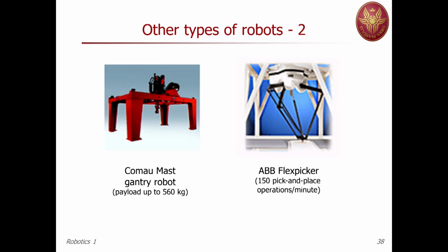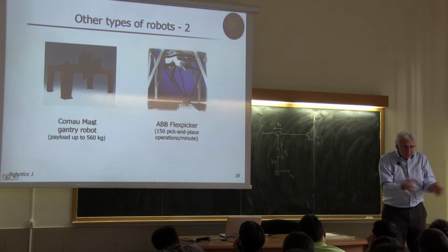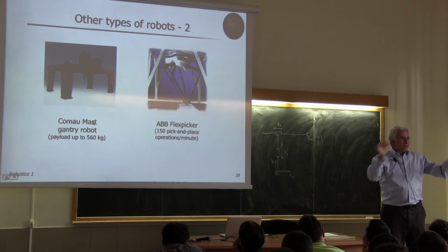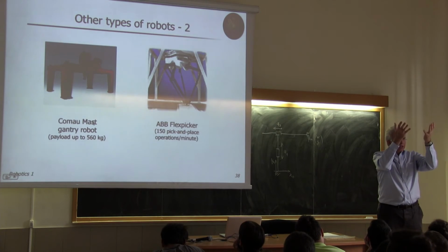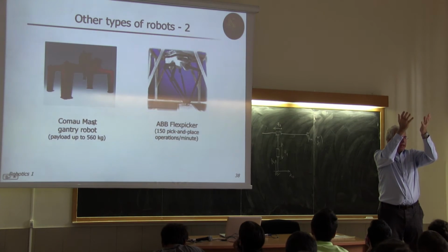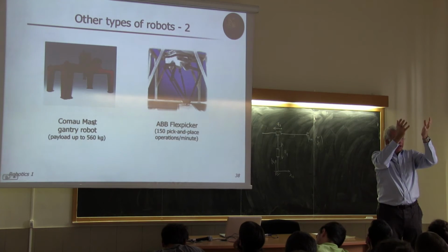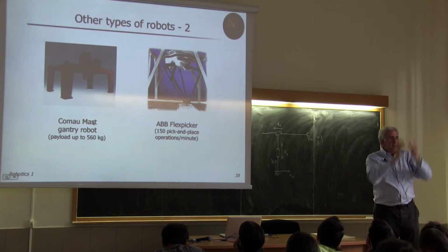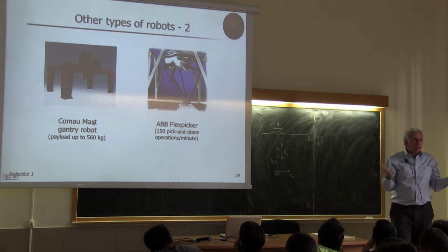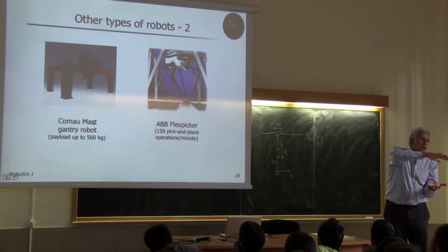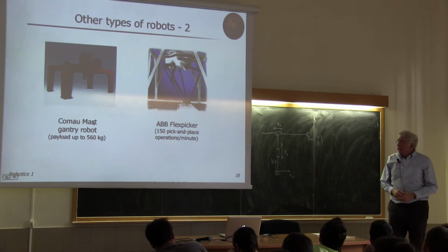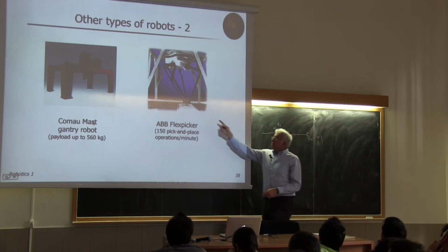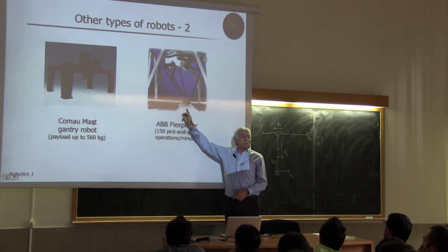Okay, which means that the whole structure may be very light because there are only these almost wire-like, very thin aluminum links that need to be moved, with motors that are always suspended. They are carried around, suspended within the top box, which is the plate of the structure. You can reverse this and imagine it on the floor, but it's irrelevant. Okay? And in fact, this kind of structure allows very fast pick and place operation.